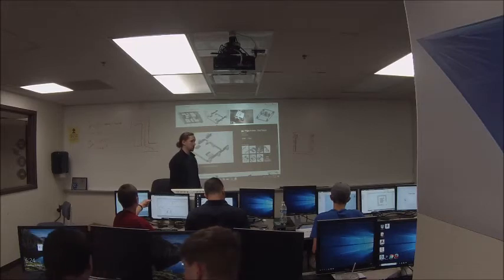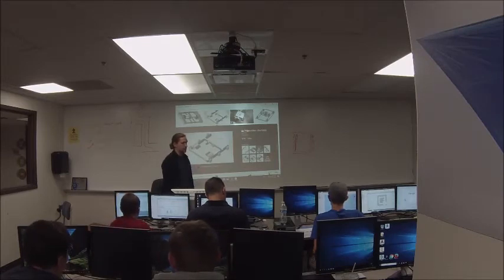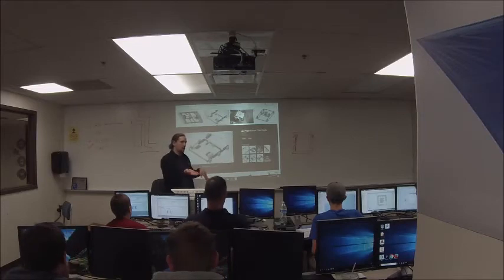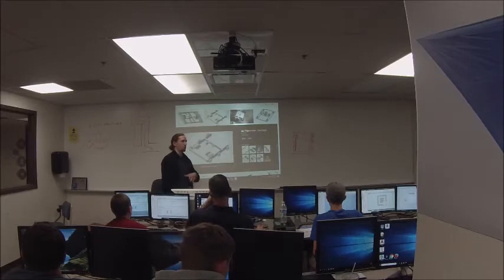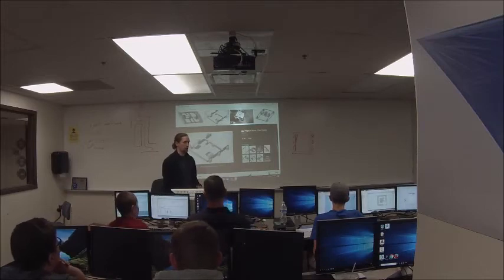But they're extremely maneuverable. Now, technically, and I mentioned this before, they're semi-holonomic because they don't have the ability to move in any direction at any time. The reason is you have to wait for the wheels to turn to face the correct direction before you can start moving in that direction. In practice, they move very fast, so you can't really notice it. It is very slight, but it is there.